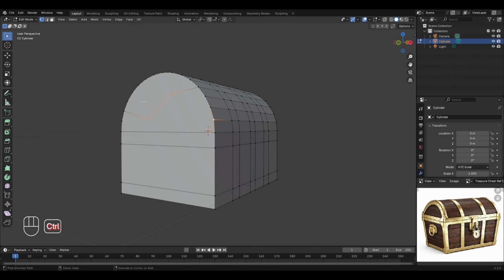So for now, I'll press Ctrl+Z to undo this, and we'll now use the knife tool to join these 2 points together. So press K to enable the knife tool. Then first of all, I'll take this tool to that particular vertex, then left click, drag the cursor away, and we'll take this point to the other vertex. Then left click and press the enter button. By doing this, we now have both of these points connected with each other.